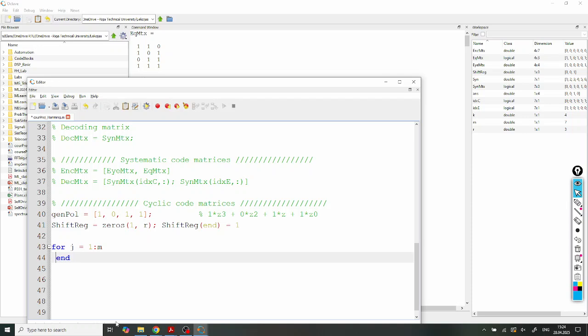So first, what I want to do is to take my shifted register content, append the 0 at the end of that, and save that as some number, let's say A. It doesn't matter what exactly. Now from this number A, I want to read as the shift register new value all values except the first one. Yes? So like that.